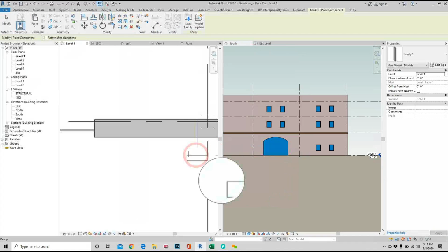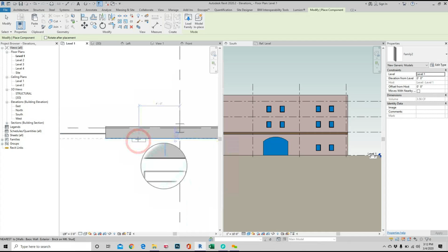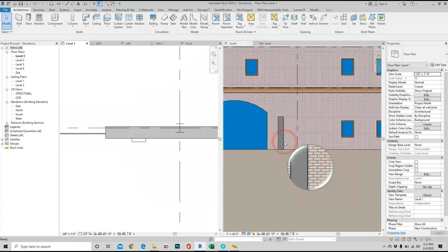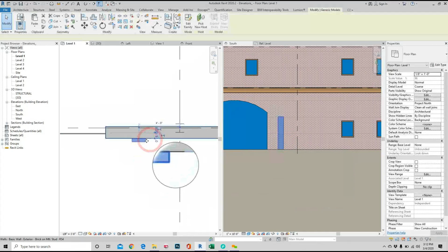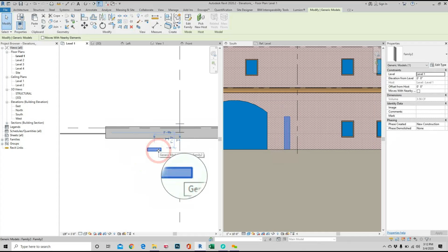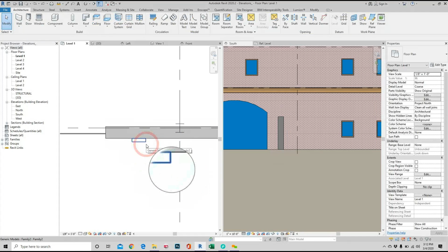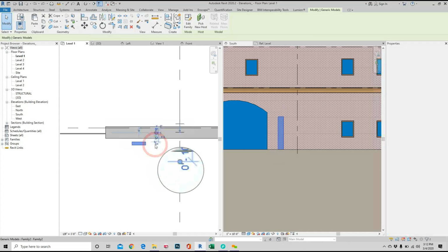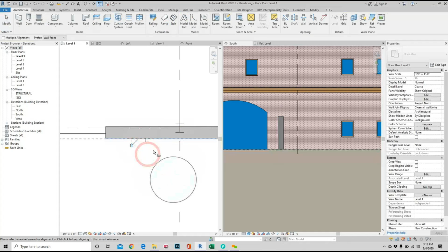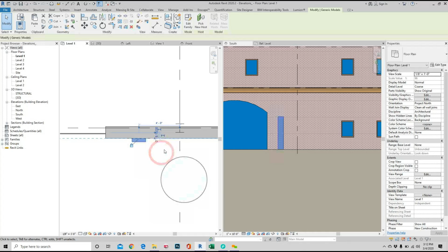All right. And then I'm going to go to the plan, and I'm going to put it right where I want it to. I think I wanted it here. There it is. All right. I just created that. It's attached to, I just put it right on it. Notice that this one I can move around, okay? Because I didn't make it hosted, okay? So that's a decision you're going to make. So I can make it in a way hosted if I align it and lock it. So for example, if I align this to the face of this and lock it, now it's hosted. I cannot move it, right? I cannot move it out, all right?